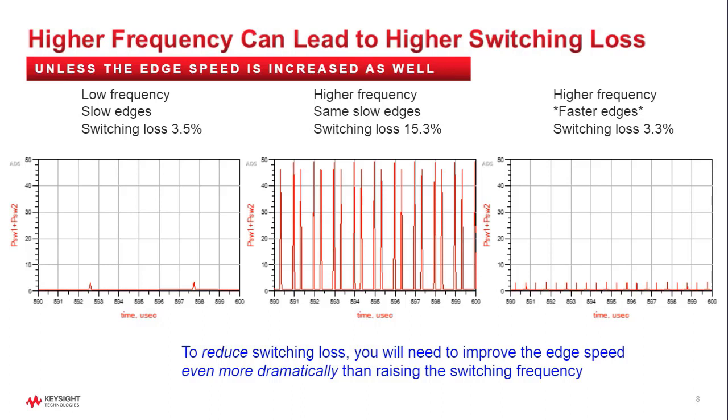If I'm not switching the transistors on and off properly, if I'm not switching them fast enough, I want this edge speed to be such that the two transistors in a half wave or the four transistors in a full wave are switching fast enough so that everything's switching synchronously and I don't have one leg on while another leg is still on. If I don't do this right,